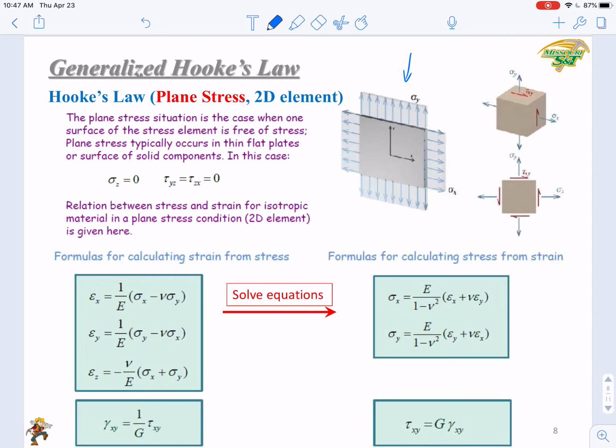If we have sigma z equals 0, logically you can get two equations. First of all, this goes from the complicated three-dimensional generalized Hooke's law to a two-dimensional plane stress Hooke's law. This is actually what we derived in the previous example in earlier chapters: when you have the loading along the x1 direction, how can we determine the strains and deformations along x1 direction?